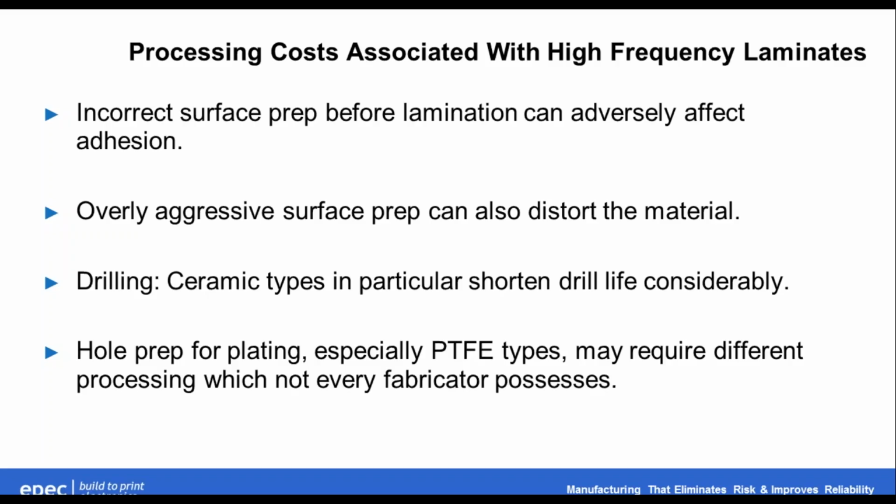A lot of the fun with these materials is learning how to drill them. Ceramic types in particular shorten the drill life considerably, and the hole preparation may require different processing that not every fabricator possesses. And by hole prep, I'm talking about de-smearing the hole.